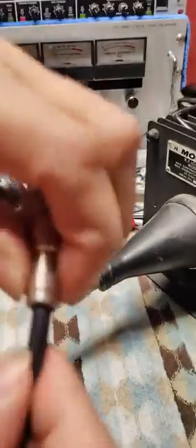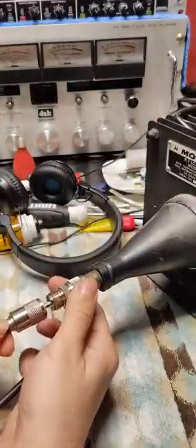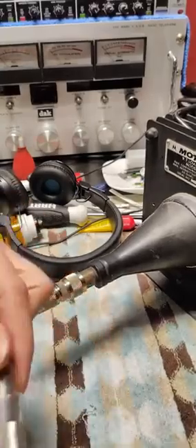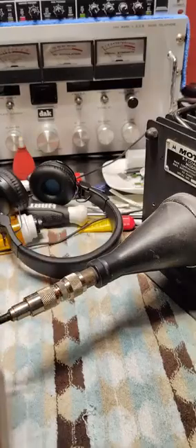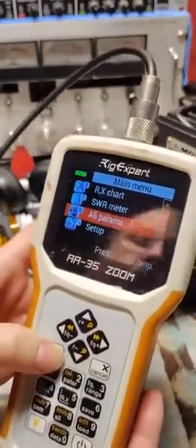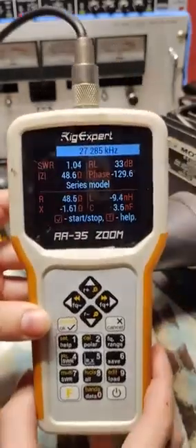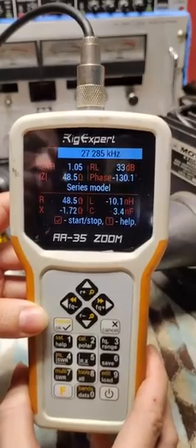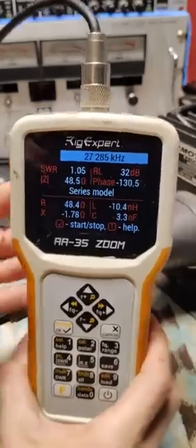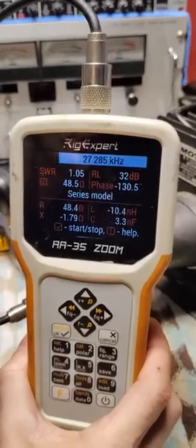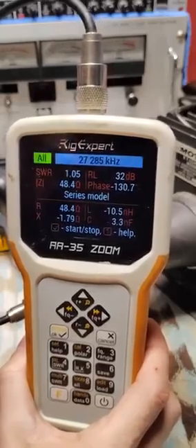Anyway, she's good. She don't wiggle. This is a good jumper, soldered as usual. This is about a 3-foot one. We're going to see what this piece of coax tells us. Y'all think it's going to change? I know it will, because there's reactance at play. Look at that. Now we've got 48.6 ohms. Now we've got reactance taken away from the load. Look at that. Of course, a different phase angle. Much shorter piece of cable.